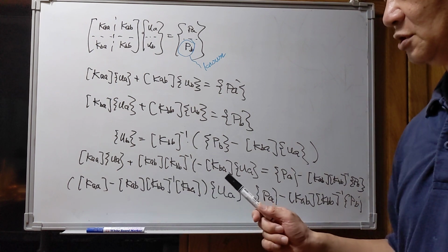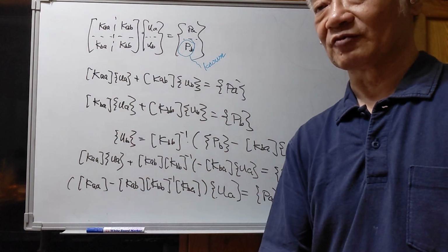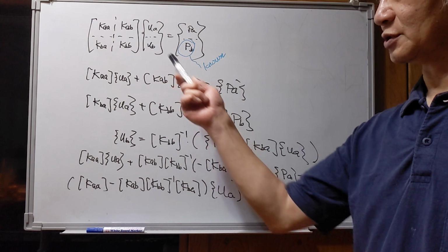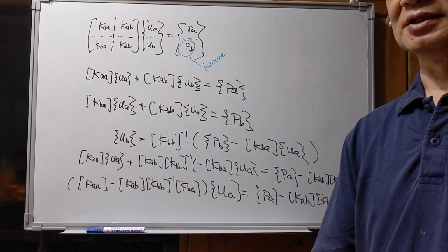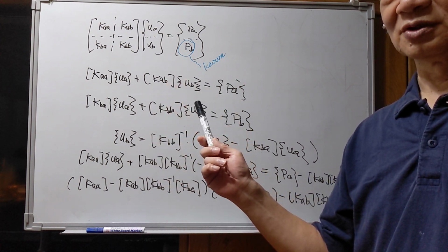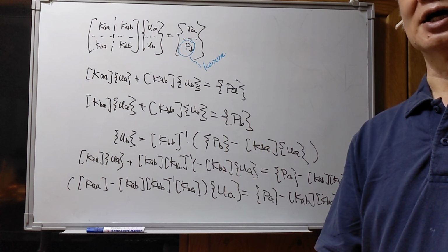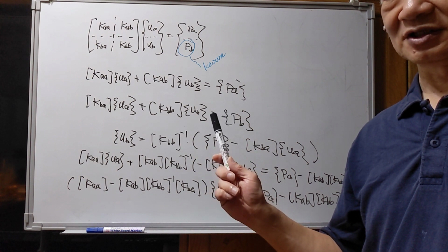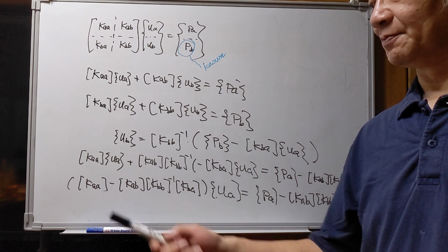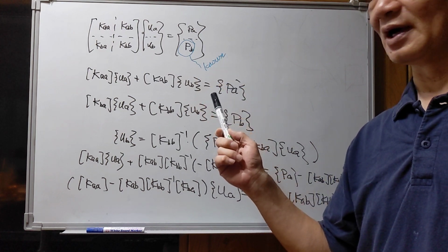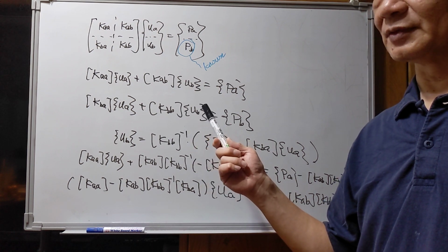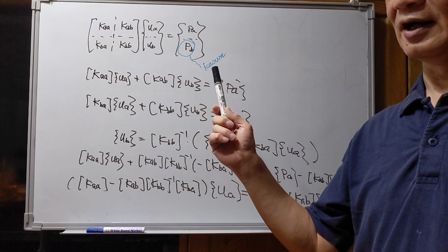This condensed matrix has a smaller dimension. If you check most reference books, when they discuss static condensation, you will see this kind of derivation. But in my opinion, you can use these steps to explain what you need to do, but in the actual calculation it is not a very effective way to solve static condensation problems. Last time I didn't even write this formula, but I think it is good for you to know there is an expression, to explain why it is not very efficient.